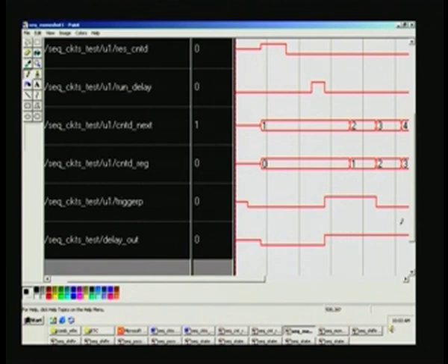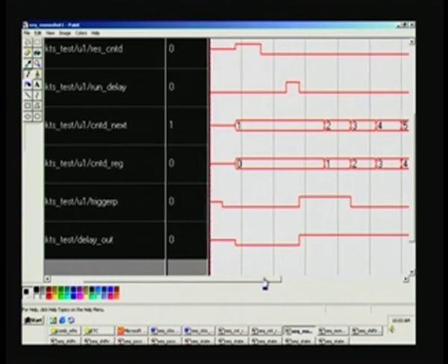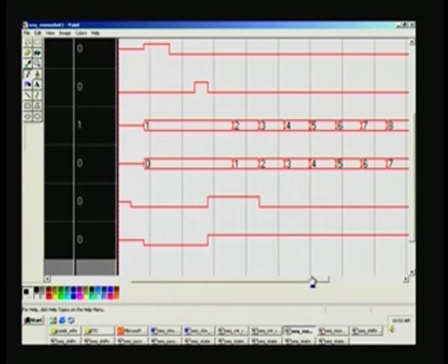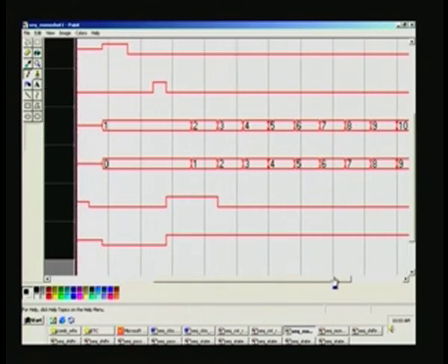This proves that whatever the setting is, you get precisely that, right. And now another point: suppose earlier I said 256 cycles. Why that happened is the code was different. I did not take that reset counter as an asynchronous way of setting. Earlier I had taken the reset counter inside itself, so when reg is 255, I make a decision only there.